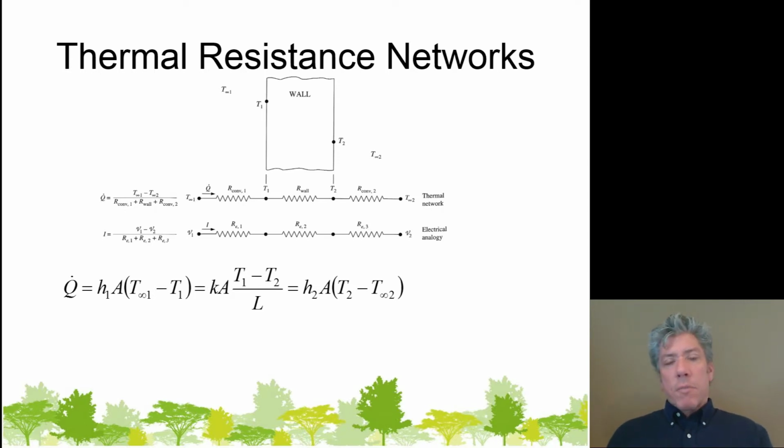And I think the reason that a lot of people struggle with this is because they realize the outdoor temperature of the walls is lower than the indoor temperature, so they feel like, well, it's colder, so heat couldn't transfer as fast. Well, remember that the air outside is colder still. The surface temperature of your home, if you keep it warm, even on the outside, is at a higher temperature than the surrounding air. It may be difficult to detect, and it may vary along the entire surface, but that's still the case. So the point here is that the heat flow through this resistance network, which is just a series circuit, is exactly as it would be with our electrical analogy.